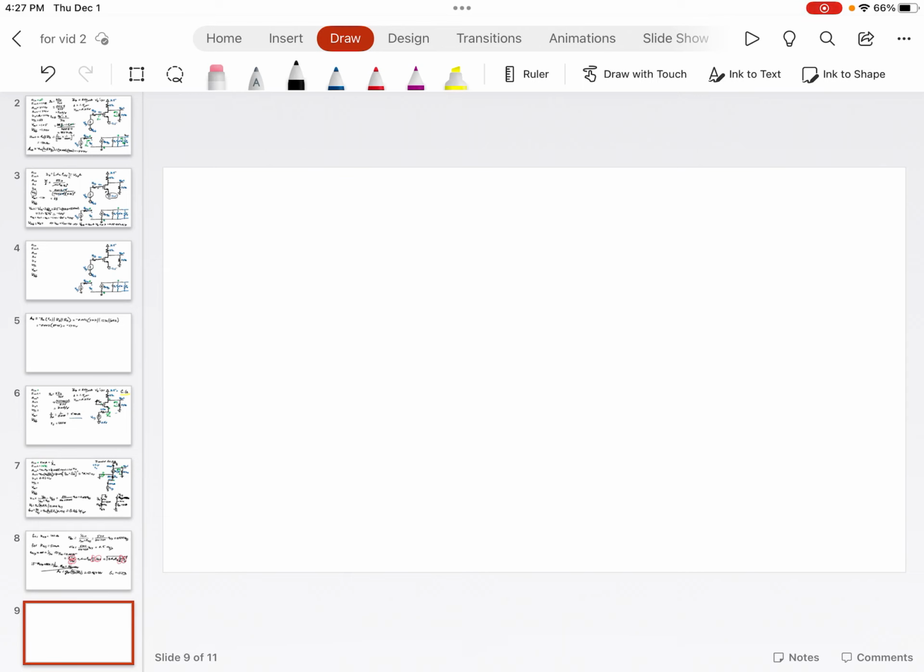What would some of the design choices look like if we had 1 over GM, going back to that one, equal to 500 ohms? Then we need GM equal to 0.002. If we needed the 1 over GM to be 400, then GM is equal to 0.0025. And we could, for instance, stick with 0.25 overdrive.